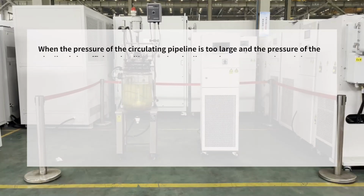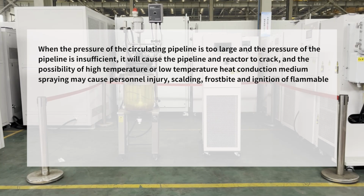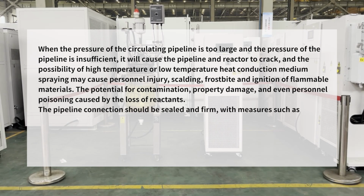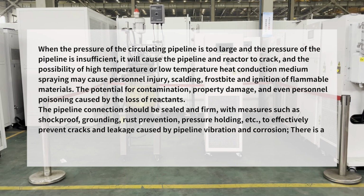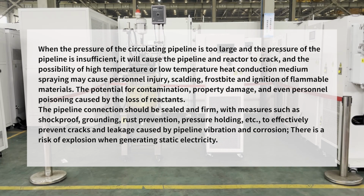When the pressure of the circulating pipeline is too large or the pressure of the pipeline is insufficient, it will cause the pipeline and reactor to crack, and the possibility of high temperature or low temperature heat conduction medium spraying may cause personnel injury, scalding, frostbite and ignition of flammable materials. There is the potential for contamination, property damage, and even personnel poisoning caused by the loss of reactants. The pipeline connection should be sealed and firm, with measures such as shockproof, grounding, rust prevention, pressure holding, etc., to effectively prevent cracks and leakage caused by pipeline vibration and corrosion. There is a risk of explosion when generating static electricity.